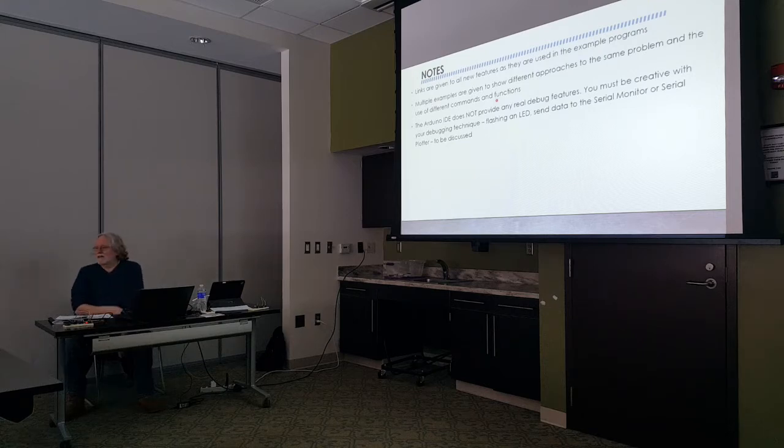The Arduino IDE has no real way of debugging except flashing the LED and the serial monitor and serial plotter. If you were actually doing this with a development system, you could set a breakpoint, and it could run to a command and stop, and you could look at your variables.